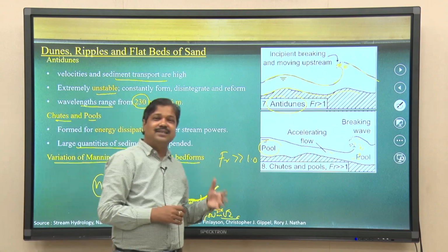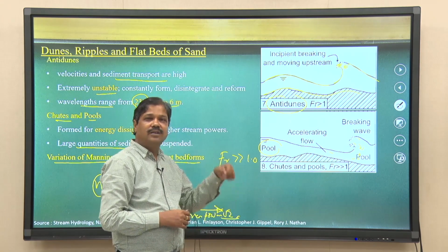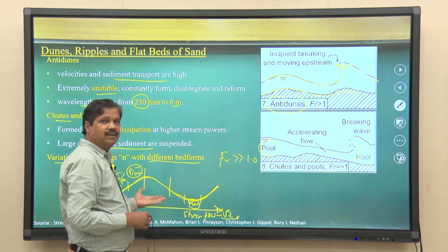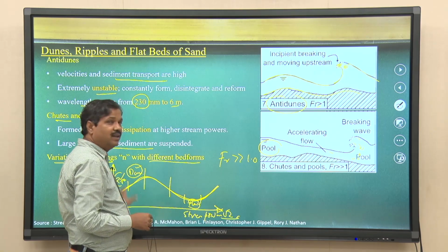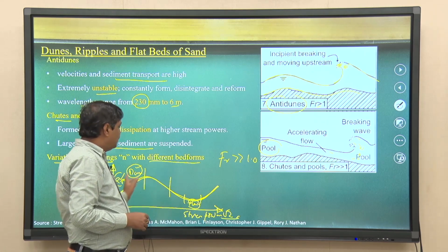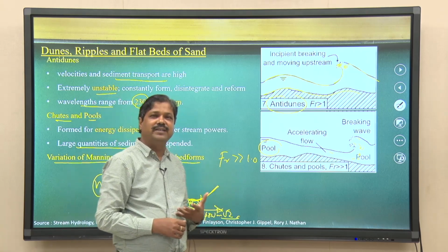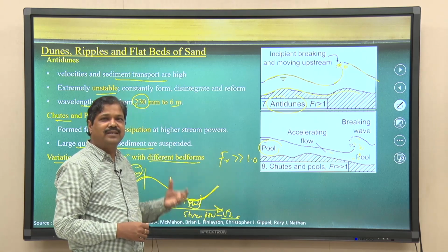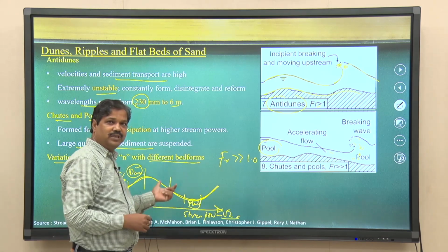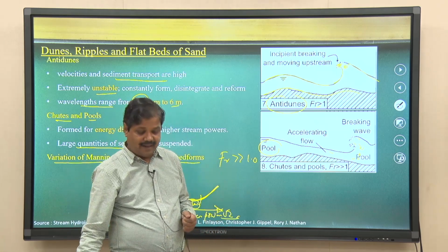That is the reason the river shows a lot of nonlinearity when you observe the stage discharge curves. Because the bed is changing from ripple to dunes to antidunes to plane surface, the n value also varies. As you can interpret from Manning's equation, the velocity and the flow depth are related with n values, so n value variations are indicated by that.